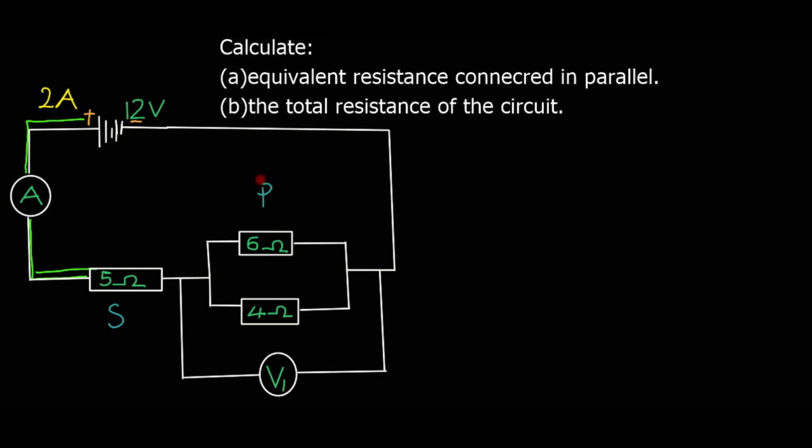So it's important to understand that current in series is the same. This means this resistor, because it's in series, you should measure the total current. Total current is 2 amperes. This resistor you should measure current 2 amperes. This current all flows through, but at this point it splits, meaning it divides, because this resistor and this resistor are connected in parallel. Always in a parallel connection, the current divides.